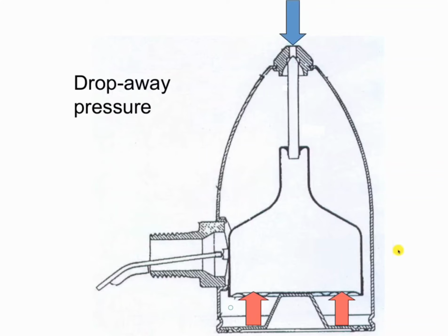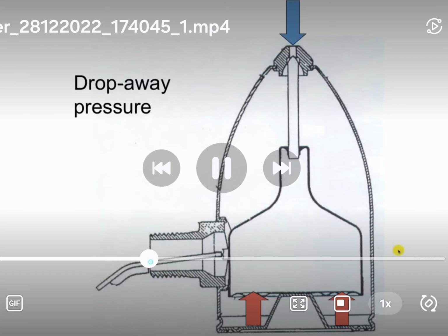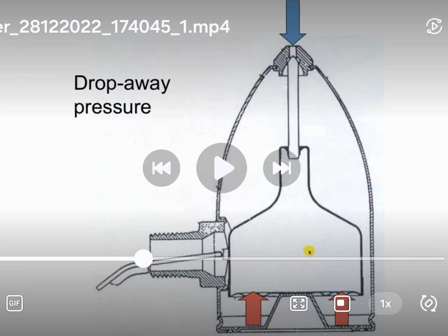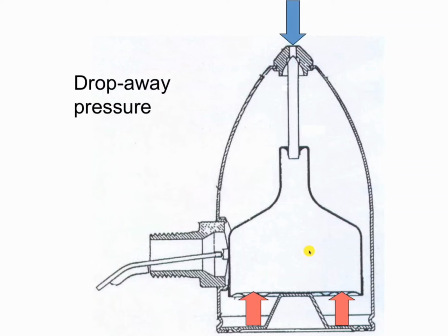Let's continue. Let me bring it back for a second. So that which came in at a constant pressure and never dropped, the constant pressure just held the vents closed, and before the air is out, the radiator's full of air. That's the next thing I'm curious about. A constant pressure. Anytime you deal with steam, especially Con Edison steam, you are talking about steam that's running under the street at excessively high pressures. These are dangerously high pressures. Nothing that you can play with.